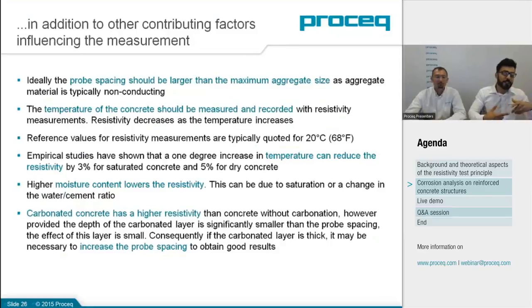Now, in addition to the rebar, which is one of the main contributing factors, there are other elements as well that we need to take into account because they contribute to the health of our inspection. The probe spacing we've mentioned several times. Probe spacing should actually match our aggregate size. In fact, probe spacing should be larger than the maximum aggregate size that we're dealing with. Environmental temperature, we covered that earlier. That is actually one of the main factors